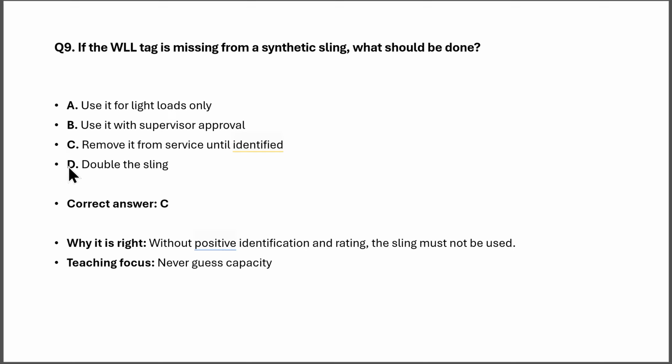D. Double the sling. Correct answer is C. Why it is right. Without positive identification and rating, the sling must not be used. Teaching focus. Never guess capacity.